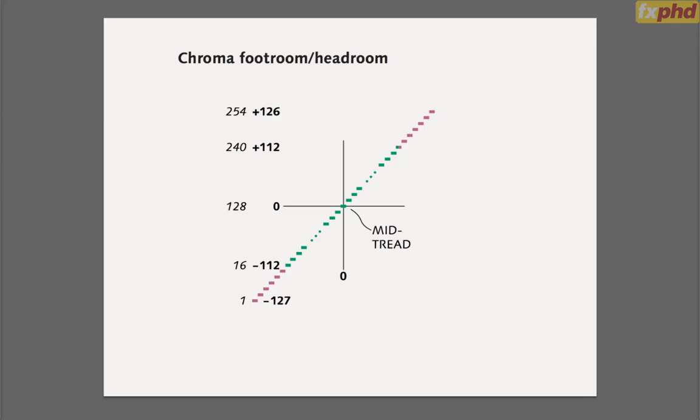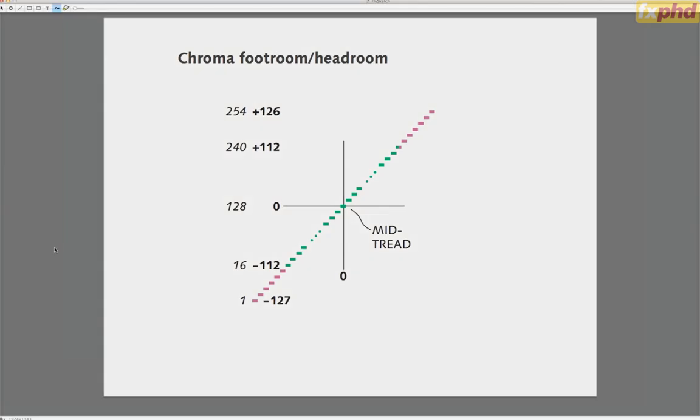Now, I was mentioning the headroom and footroom business. Just like there's headroom and footroom in the studio video levels, we've talked about R prime, G prime, B prime across the wire, to the connector, and here this would be, say, an HD-SDI link. Across the wire, those guys like talking about black being code 16 and white being 235 on the 8-bit coding scale.